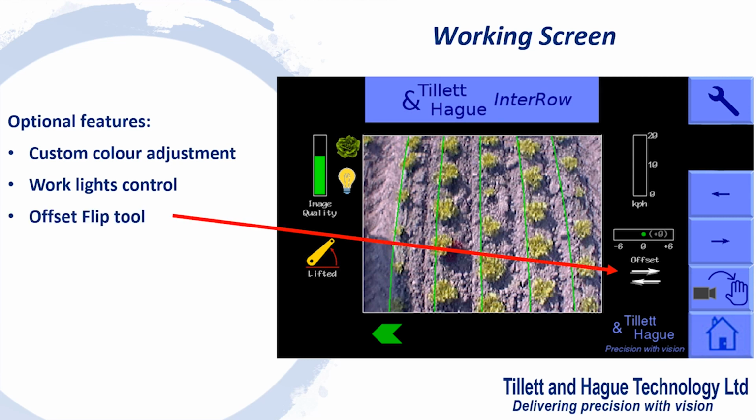The third option is a fine offset tool that adds a flip touch button under the fine offset bar, which when touched flips between the 2 different fine offset values. This is useful whenever bias regularly alternates between 2 states. For example, working on side slopes or in tall crops blown by a crosswind.